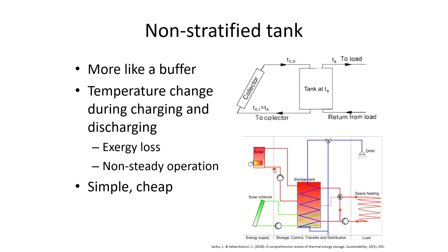Then the second option is a non-stratified tank, which works more like just a buffer, whose temperature is changing during both charging and discharging. As you have the mixing of the fluid at a certain temperature while the high temperature fluid goes in, of course there is some exergy loss, and as this tank is changing in temperature, the operation is definitely non-steady.